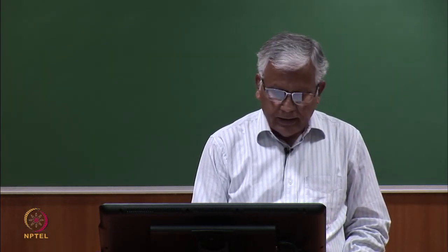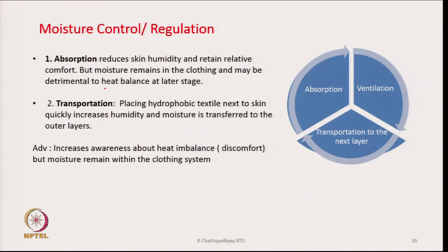it may be detrimental to heat balance at a later stage, because if it absorbs the moisture but does not release it fast, then moisture will accumulate, and after some time the moisture may get condensed into water, and then the trouble will start, because now suddenly the insulation value will go down. So, these are the problems which will come.